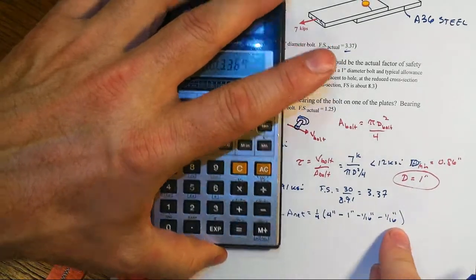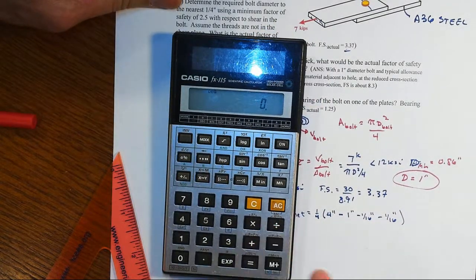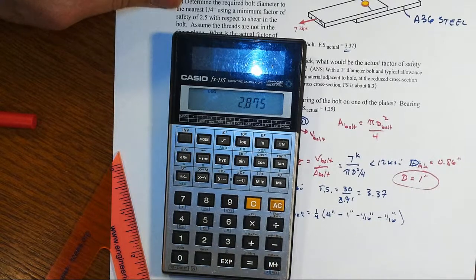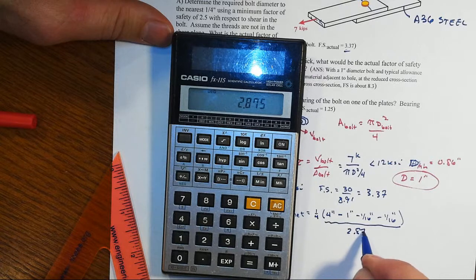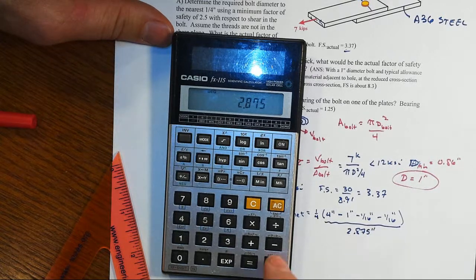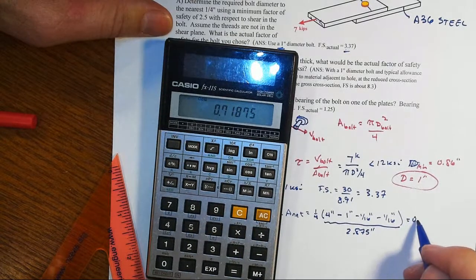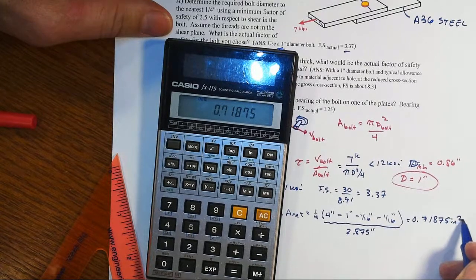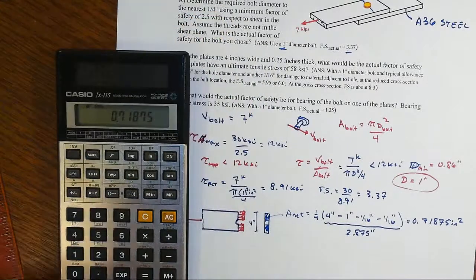So there's an effective larger hole: there's your hole diameter, 1 1/16, plus the damage that we have there, that's 1 1/8, so 1.125 that we're going to subtract away from the 4. We really only have 2.875 inches that are effective there, times our 0.25 inch thickness, and so our effective net area is 0.71875 square inches. It's a little too precise, but that's the theoretical net area.